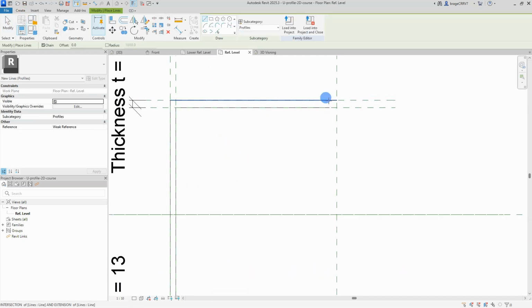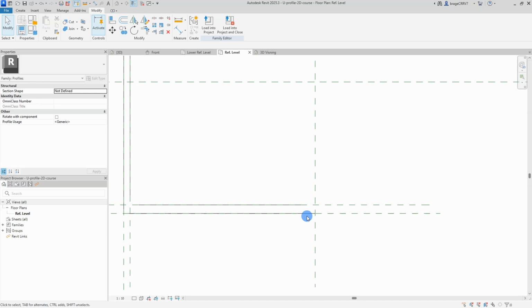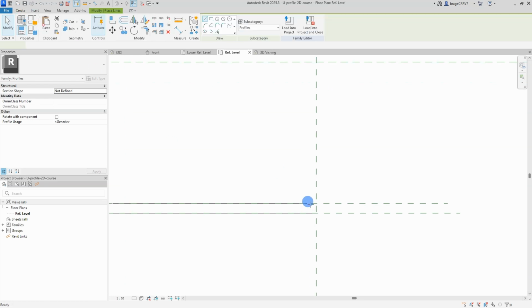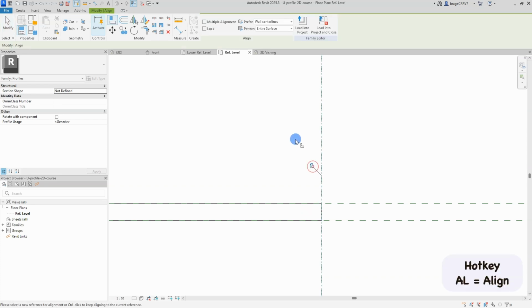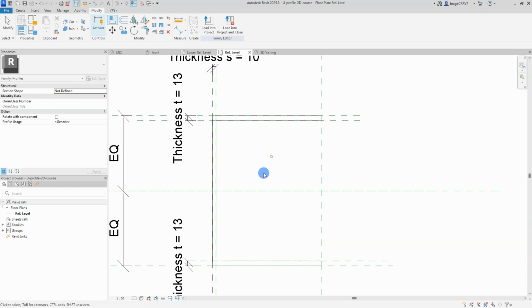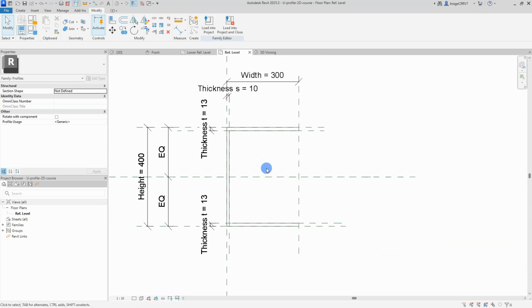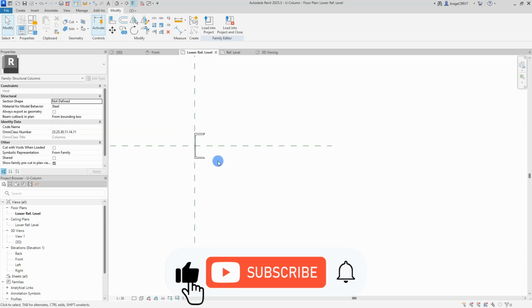And by the coarse, I really want it to be less detailed, so to make it coarse, I will remove the radius on the edges of this profile, making the edges sharp and less detailed. I will proceed by connecting the edges with the Trim Extend tool and load the profile into the column family I created earlier. I'm now standing in the column family where there is an existing column.